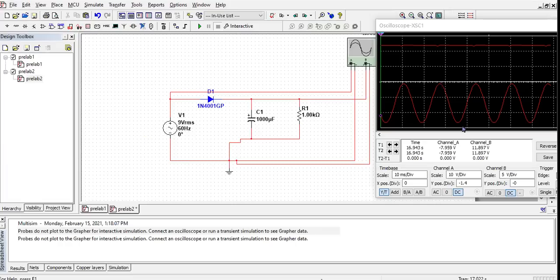So this is the first peak, and this is the second peak. If you want to measure half, it is easy. Again, make it 0. This is 0. So forget about either the negative peak or the positive peak. Just measure this one. So how much is it? Here it is cutting here. 1.2 multiplied by 10. How much will it be? 12. So roughly it is fine.